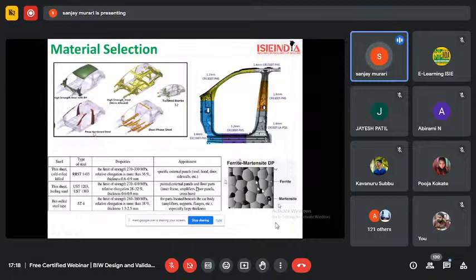So when selecting the material, we should think of the availability also. These materials are available only in a certain range of mm, so a lower limit and an upper limit will be there. In this table, you can see hot rolled steel, what range of thickness it is available in, and what its strength is. It is written over here. Based on our application and the analysis, what the requirement is, we can choose the material based on its availability.